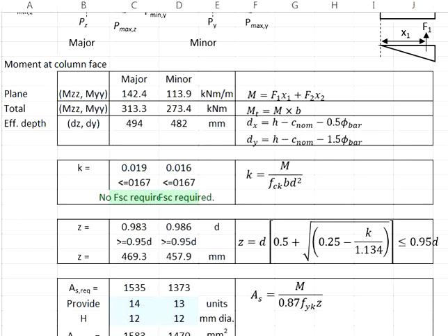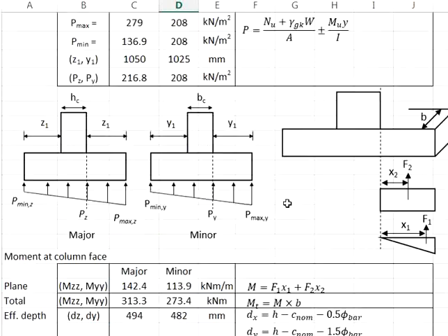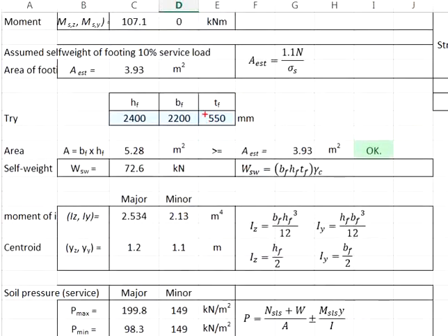More critically, the design of the pad footing is influenced by the shear resistance. In order to ensure sufficient shear resistance, normally we will provide a relatively thick pad footing.